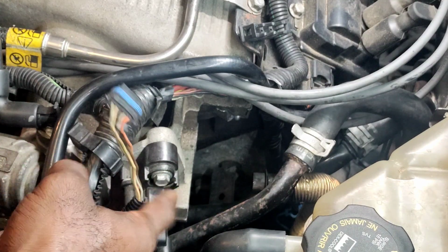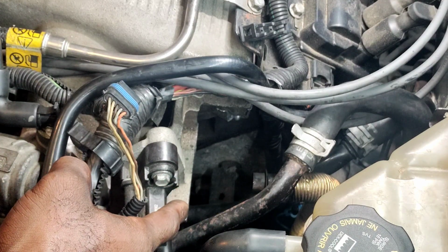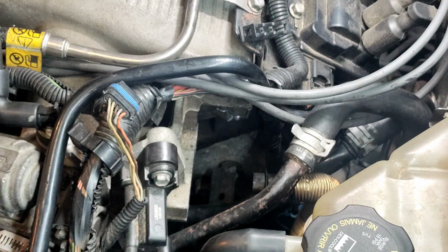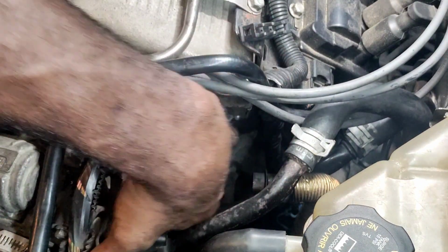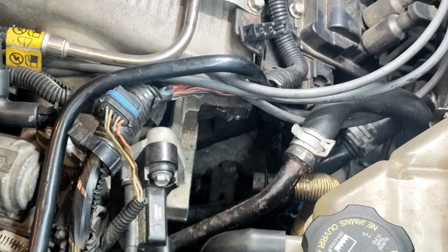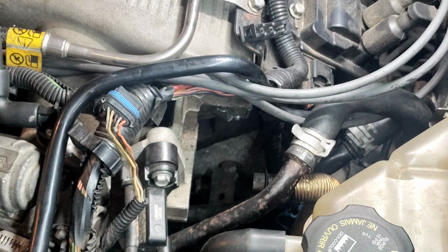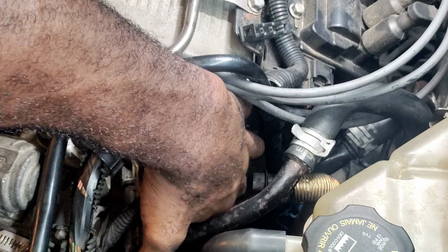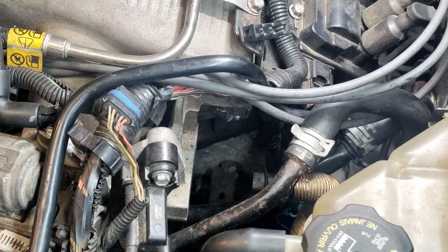Now, when we originally started it up, there wasn't any vacuum, even though the EGR had lifted itself. So I'm going to start it up, put my fingers here, and if not, then I'll take a brush or a pick and go in there and try to see what's obstructed.